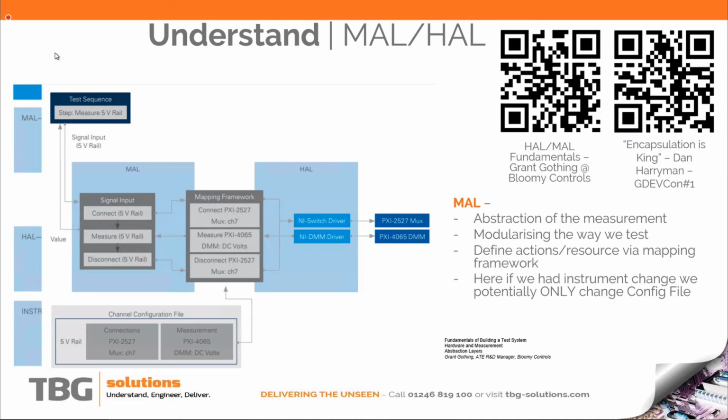We've used this type of abstraction combination for an end-of-line PCB test system where there were 150 different product variants, using dynamic test sequence calling to call a specific product variant with different mappings of pins and different switching methods that need to happen. They all run the same template frame, the same test sequence framework, but they do massively different things.